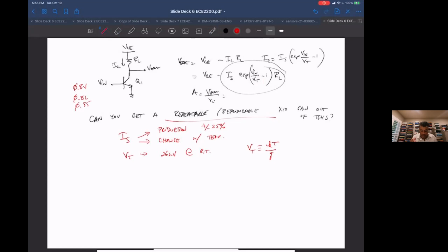And if you remember, we said a VN in a bipolar transistor changing by 60 millivolts changes I sub C by a factor of 10x. So if from microphone to microphone my starting point for VN differs by just 60 millivolts, my I sub C changes by a factor of 10 times.